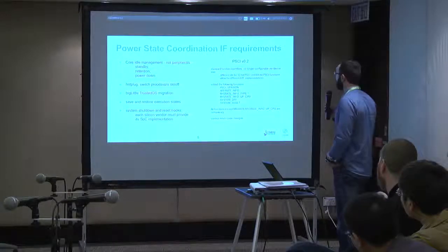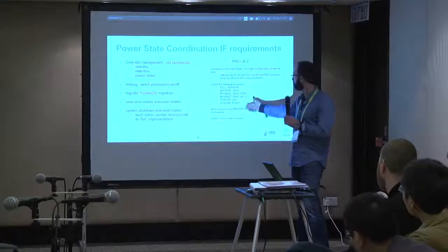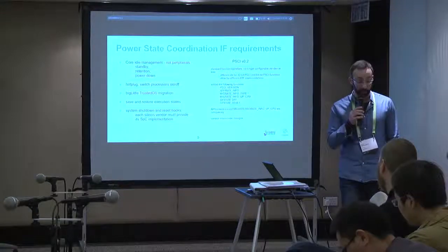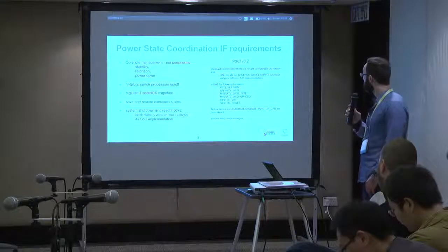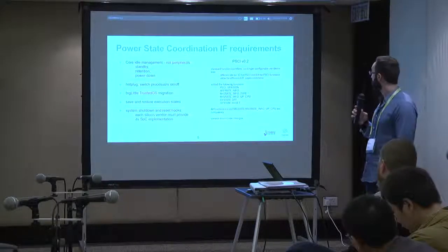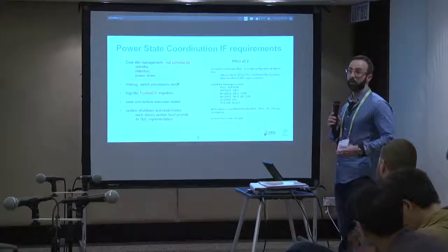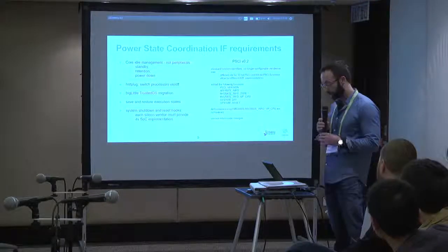They added a number of functions: affinity info, migrate info type, system reset. So all these are new functions on the interface. And all of them, except those two that I mentioned there, are mandatory. And the other change is some return codes. So if you are moving from PSCI 0.1 to 0.2, you need to take that into consideration.